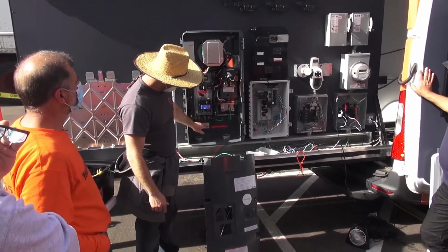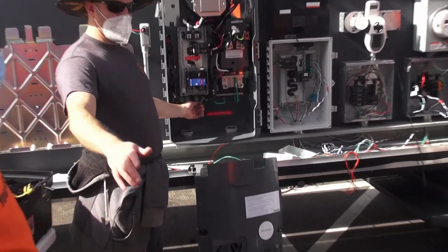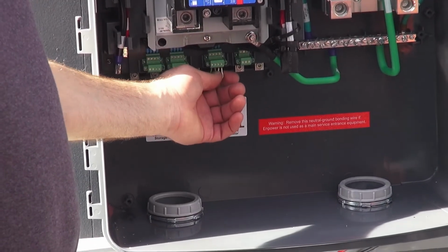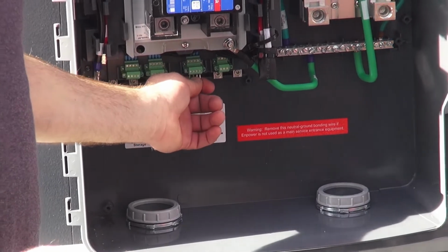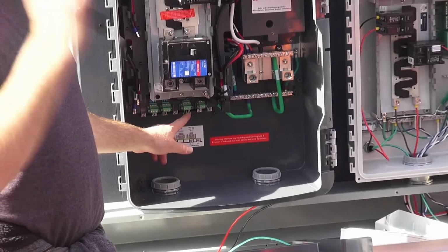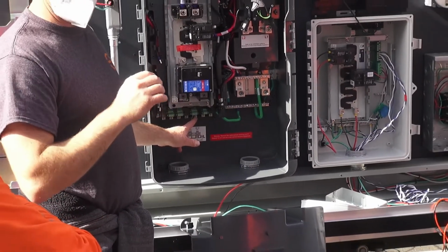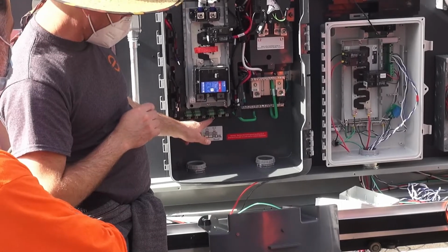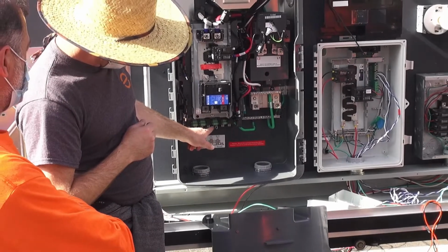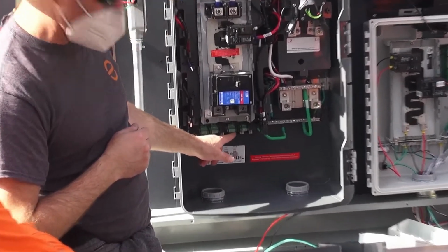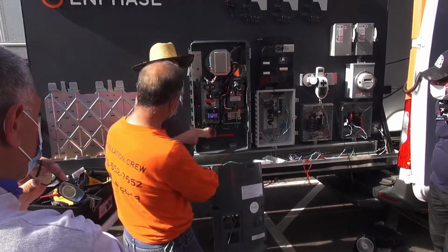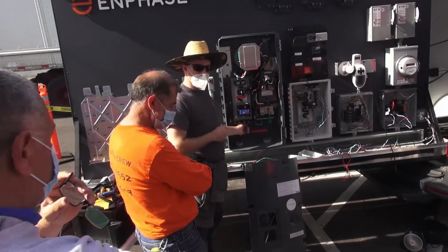It wires right here. Now, while he's recording this, these jumpers are here only because I had it configured to do a quick software update and things. I just didn't get it installed. Technically, if you're installing IQ7 or older microinverters that are grid tied only, you could use jumpers like this instead of that switch, with 2 pairs. You bridge 1 and 2 together and then 3 and 4 together. 2 pairs. Correct. But you only do something like this if it's IQ7 and older microinverters.